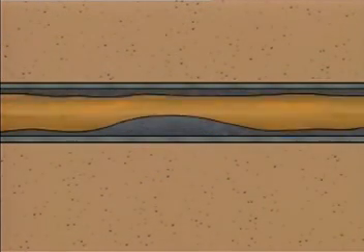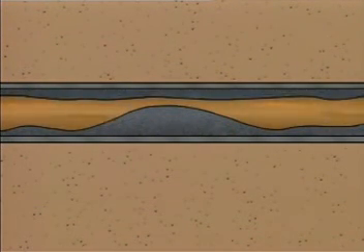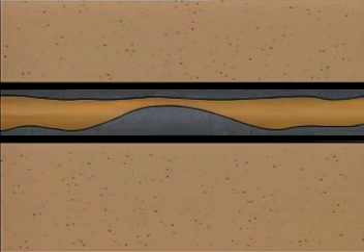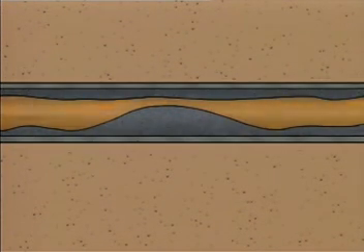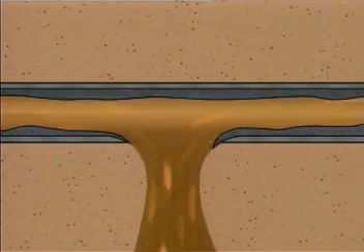Crude oil and some other types of process fluids tend to leave carbon deposits behind as they're heated and flow through the tubes. Coking makes the inside diameter of a tube smaller, and it can restrict the flow of process fluid. It can also lead to heat transfer problems. Carbon deposits insulate tube walls, which reduces the amount of heat that is carried away from the tube by the process fluid. If this situation is not corrected, the tube could overheat, weaken, and eventually rupture.